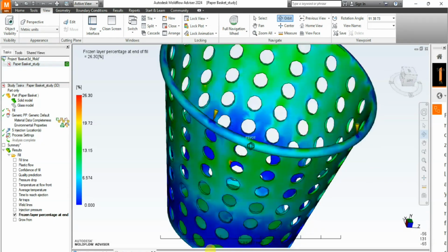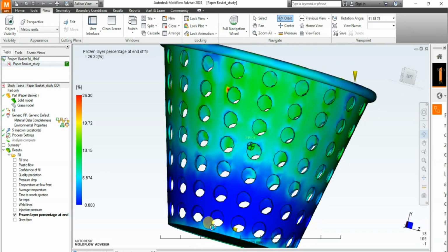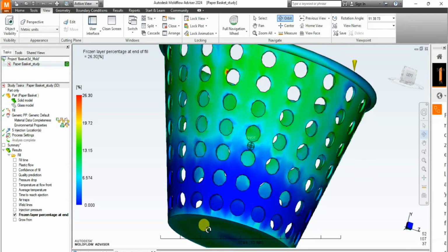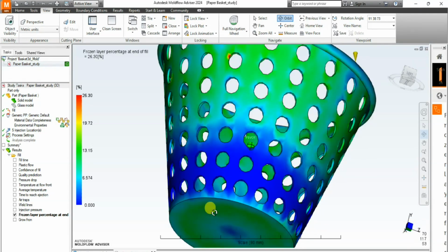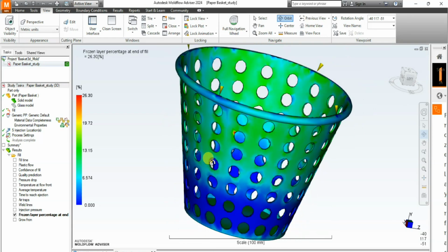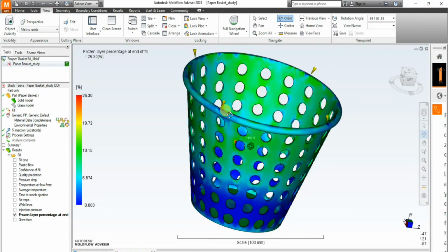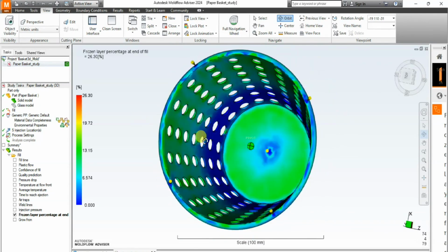Moreover, a 50% reduction in thickness in runners reduces the fluidity by a factor of 16. It is not surprising also that excessively high pressure is required to fill gates in which hesitation occurs early in the filling stage. The flow layer becomes very thin in areas of hesitation, which are filled last.